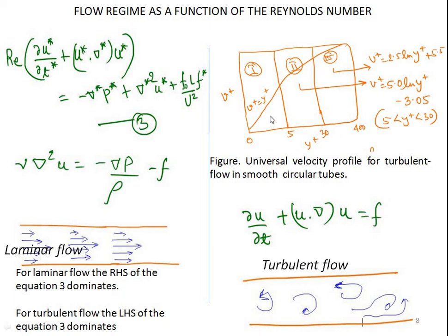The zone which is close to the wall or close to the plate is somehow a laminar sublayer. Some kind of laminar layer exists, since there are some adhesive forces between the channel material or the flat plate and the flow. So flow is not fully developed in this layer.